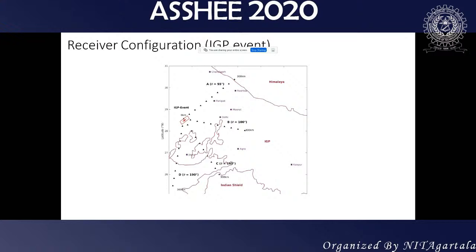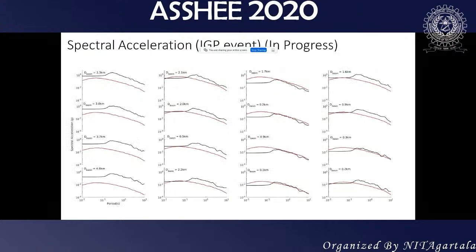If an earthquake occurs beneath the Himalaya, how much will be the amplification? So our spectral finite element model was run, and here also we have generated some 30 samples of slip distribution using our non-Gaussian slip models. And finally, these are the amplifications.